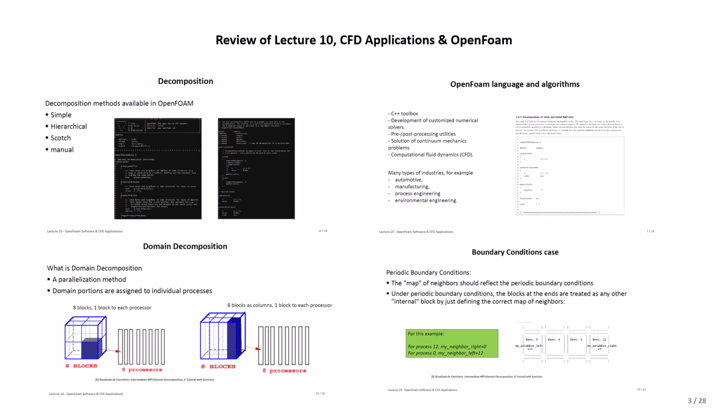And then we mentioned how the decomposition on the three-dimensional domain can be conducted, and what the effect of the boundary condition on the decomposition is, and how there are two types of boundary conditions that could be used in this regard, and we described the difference between periodic boundary condition and non-periodic boundary condition.